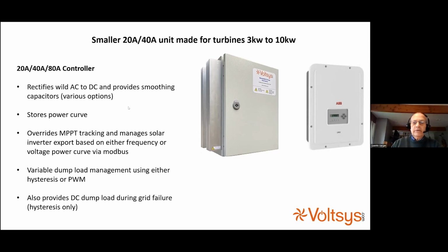So this rectifier controller also stores the power curve and has a microprocessor that manages the power curve control of the inverter. So again, we override the MPPT tracking in a solar inverter, and based on either frequency or voltage, we control the power curve via Modbus.